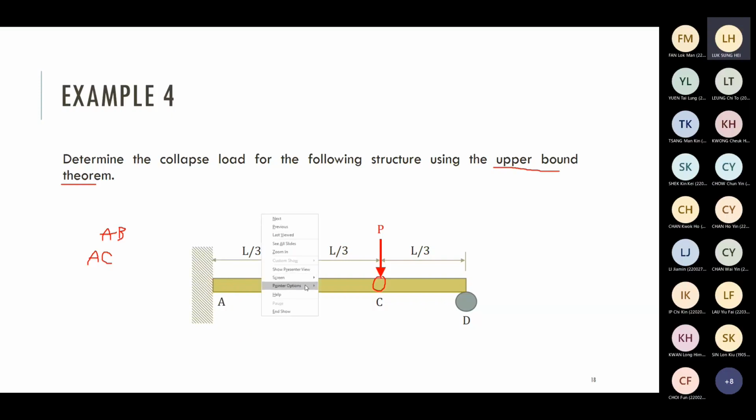In theory, the hinge may form at point B, right? In theory, also, although I think it's not possible, the hinges may start to form at point B and then point C. You may also see this kind of unstable mechanism. What I want to mention is that the number of plastic hinge is still equal to 2. The number of hinges that make the structure collapse is still equal to 2. It will not be affected by the loading. The number remains the same.